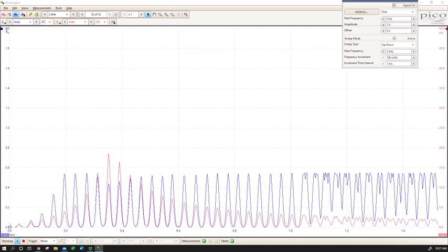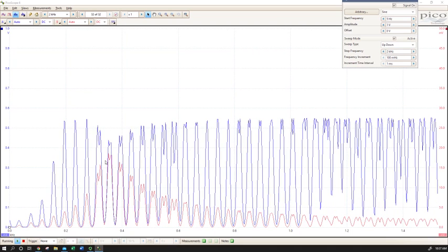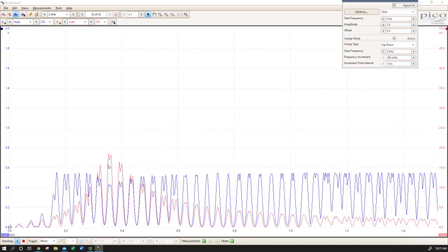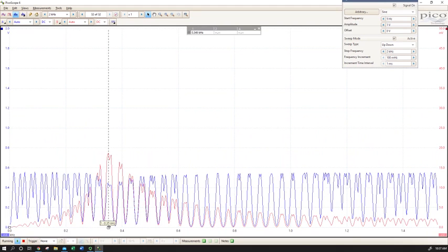So if this is real over here, we could tell ourselves that chances are we're going to have a resonance over here somewhere around, we'll call it maybe 375 hertz, and the instrument is auto scaling as it sweeps through. Each time it fills the whole screen, it actually gives a click.